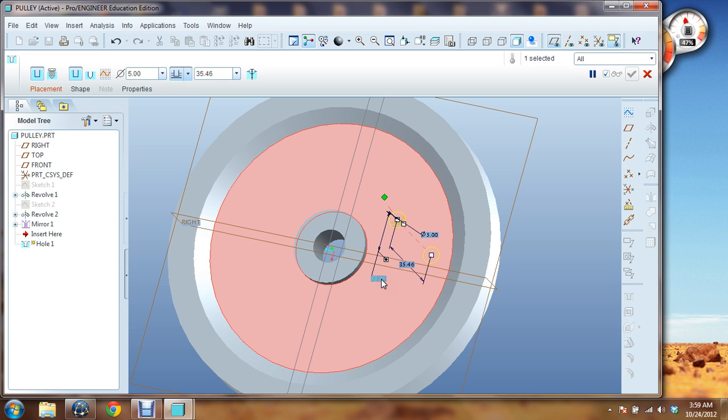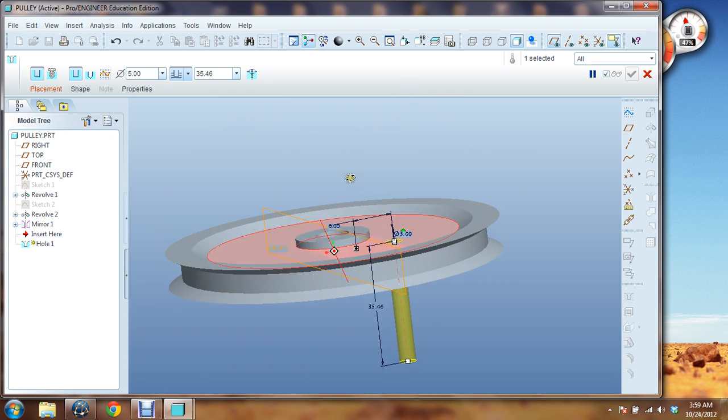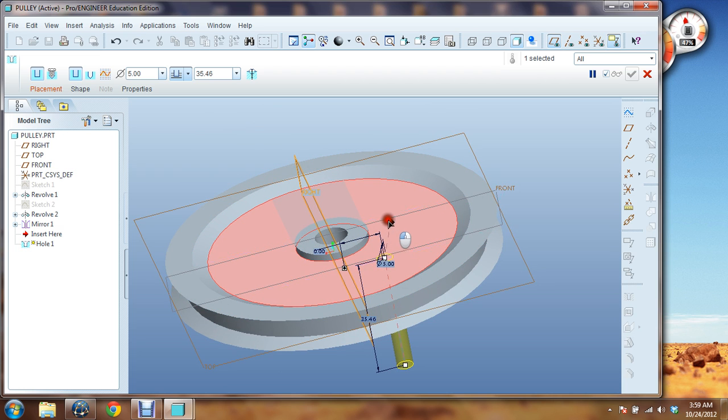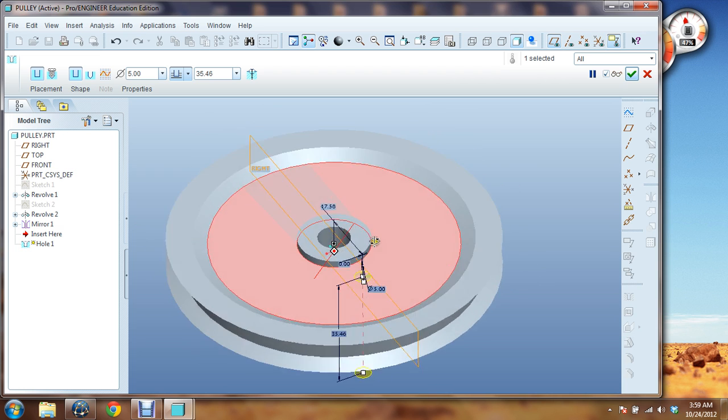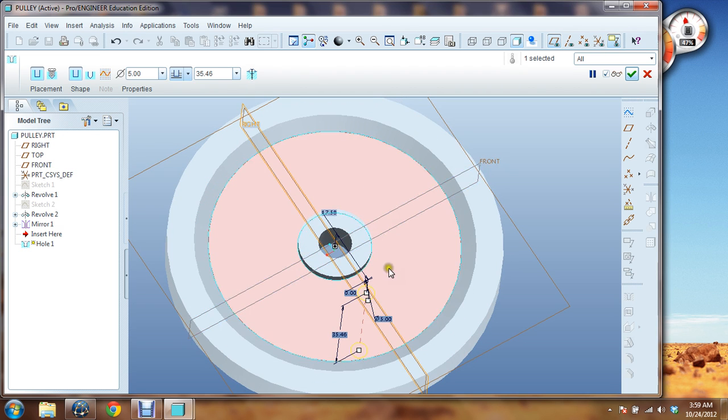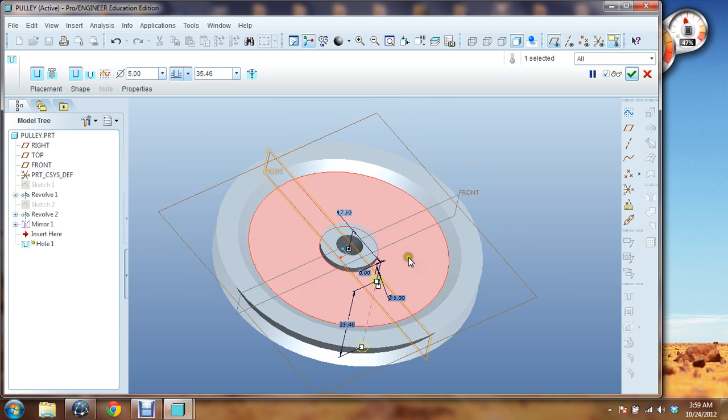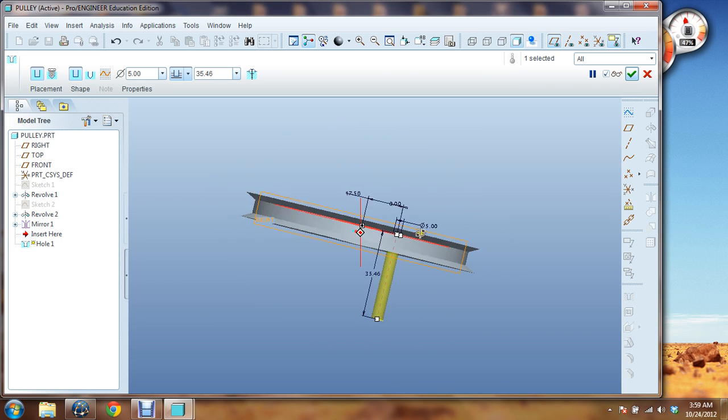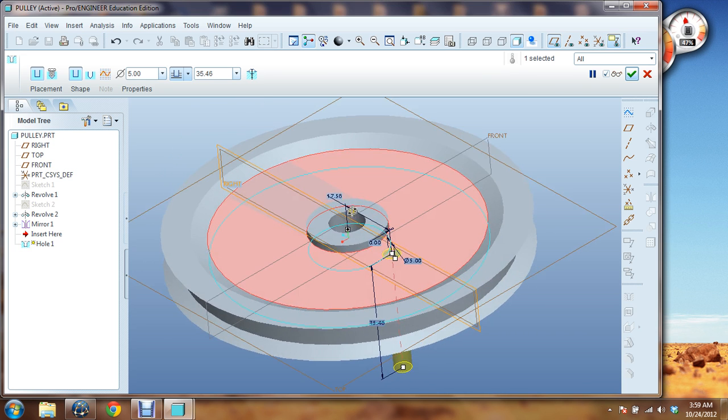I'm going to go ahead and dimension it to be 0 away from this plane. Well, actually, I didn't want to do that. Let me define it off of this plane. Okay. See, you did want to do that, but I had to define everything first. So just to redo that for you, I locked this green square here to this front plane, and it went ahead and did what I told it to do. It went to 0, and now we have another dimension over here. So it's 0 away from this plane, and now how far away do we want it from this other plane?